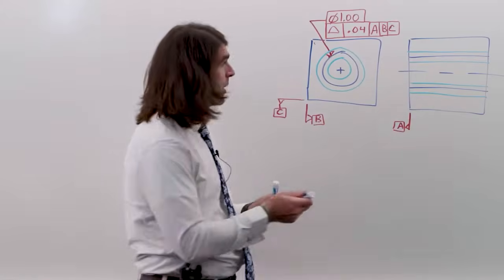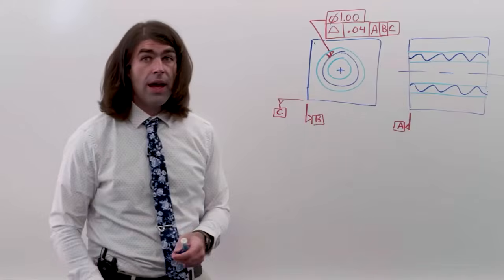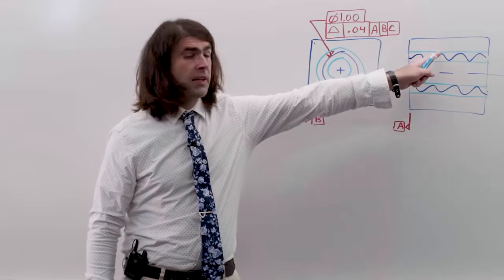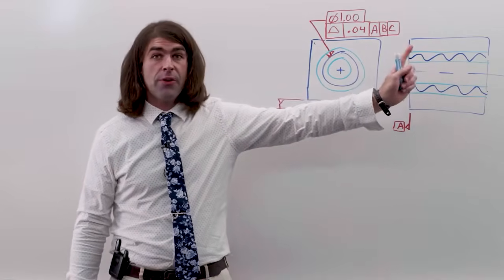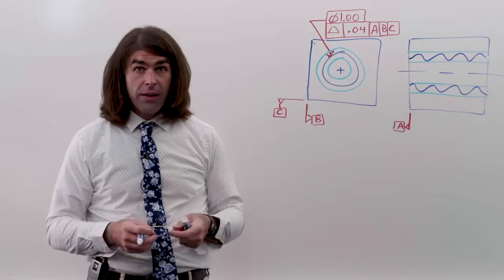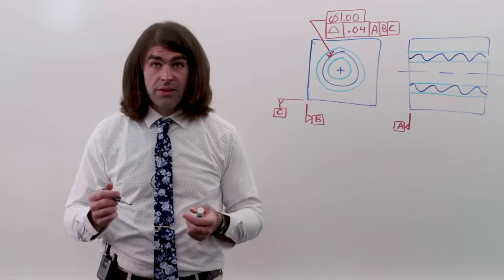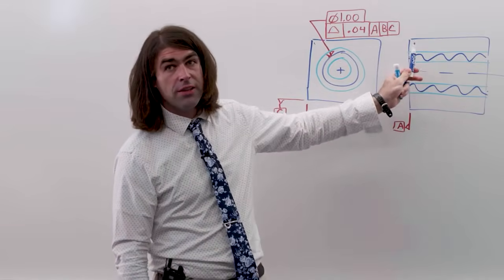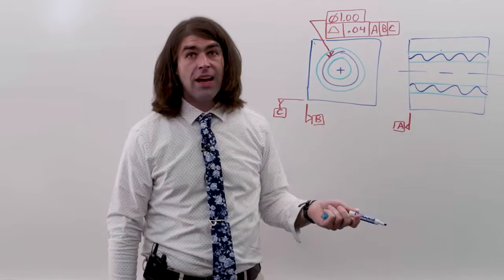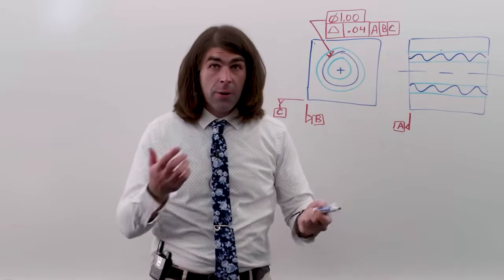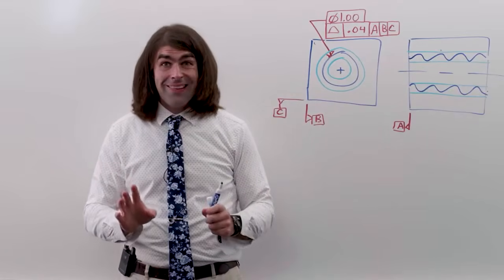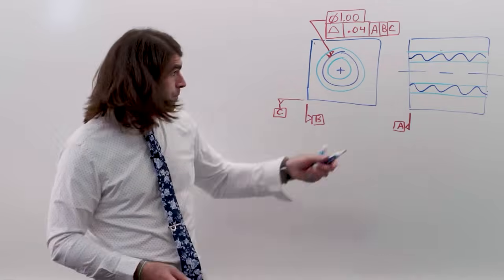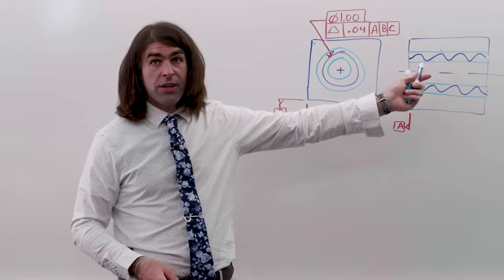So if the part doesn't come in perfect, you could have variation, but you're still looking to make sure none of the points are outside of these tolerance zones. Now this can be tricky to check without a CMM because the implication here is that you need to go inside of this part and make sure none of these low points exceed the tolerance zone of the profile. Now, position is going to work a lot different than this. What position does is separate out these low points that are essentially not functional, right?